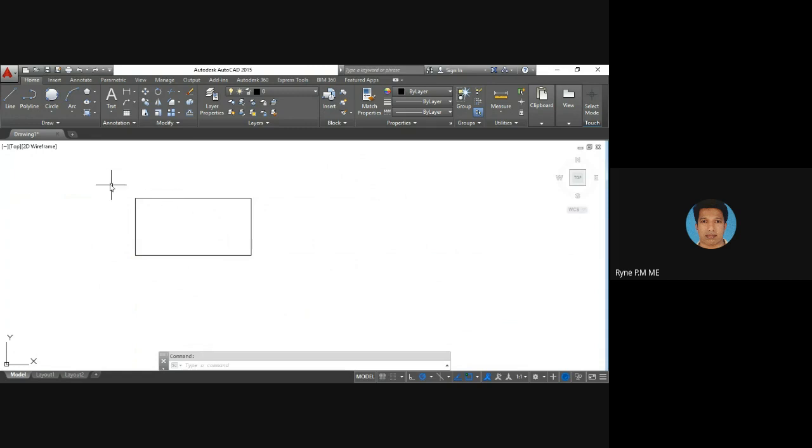Now you want to draw a box by using this one, just select the line command from here. You select that point, you bring the cursor and select this point. Then specify the next point. You want to give this angle as 30 degrees, so you can see that angle is also shown there. So for the next point, after bringing the angle to the required value of 30 degrees, you just give 20 mm, so that you can get the 30 degrees 20 mm line.